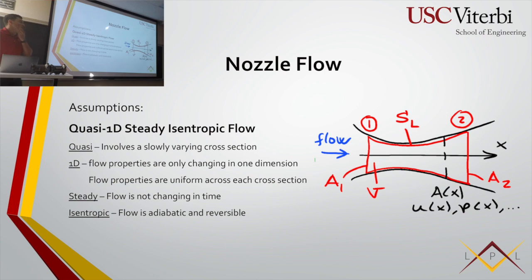And so that's where everyone sizes their engines to this because it's very close. I think it's like 90-something% correct. And then you'll have these other equations, like C_T and C star, I believe? Yeah, C_F. And so you'll have these other equations that compare it to reality, and essentially the closer you can get that number to the other one, the more efficient it is.